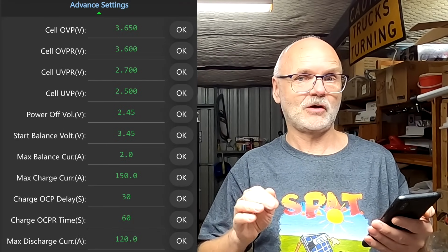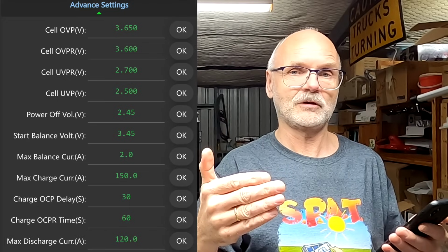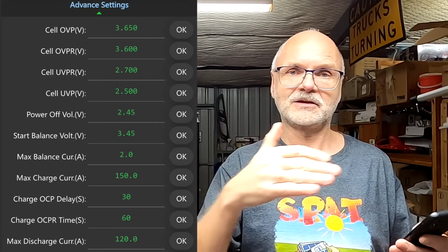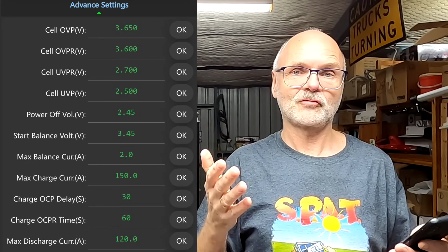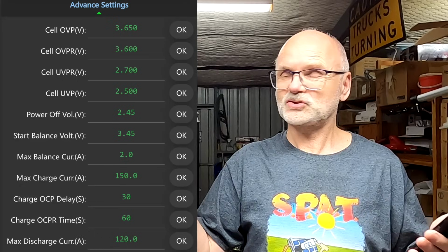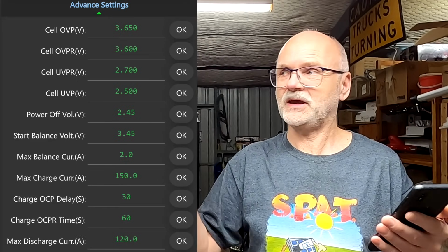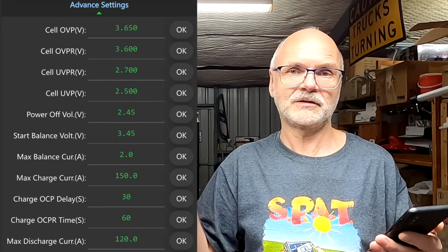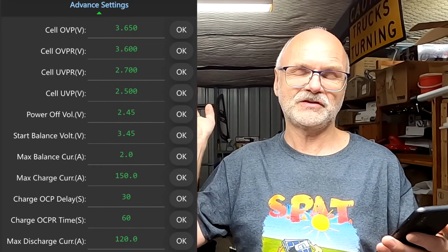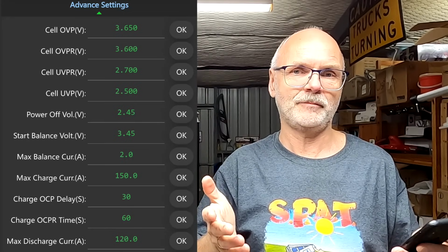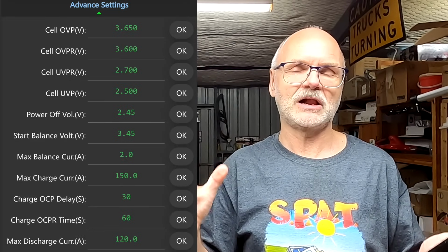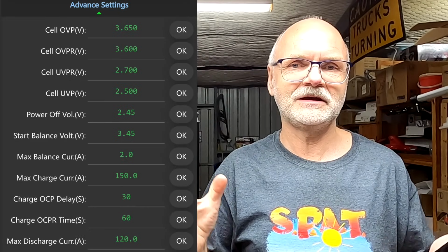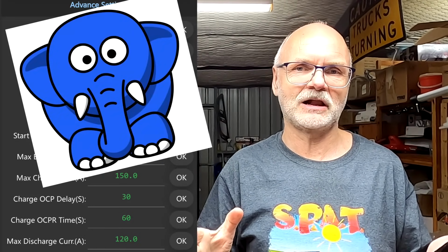If your solar charge controller charges only to 3.5 volts, for example, this is all fine. It will then stop charging your battery, right? But what if your solar charge controller is faulty? You have a surge, you have a lightning strike or something, and your solar charge controller is faulty. The next morning the sun comes out and it pushes amps into your battery and overcharges your battery until they are so bloated you won't get them out of the shelf anymore. It looks like you have 16 small blue elephants in your shelf just because you don't have a BMS.